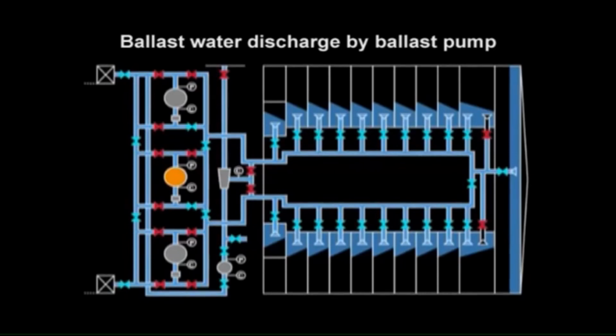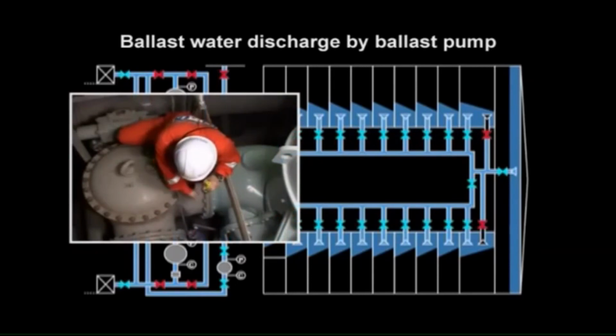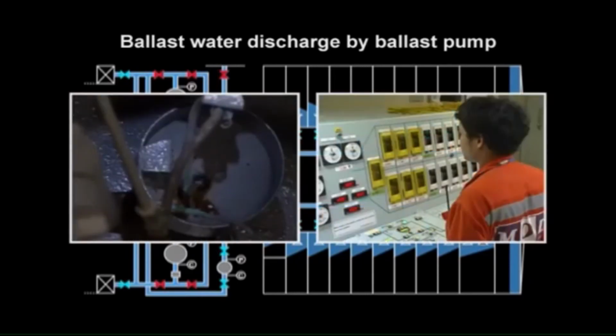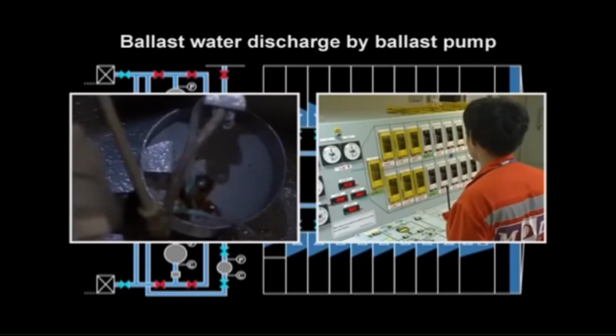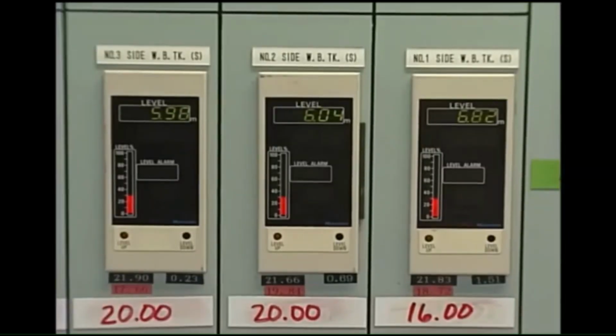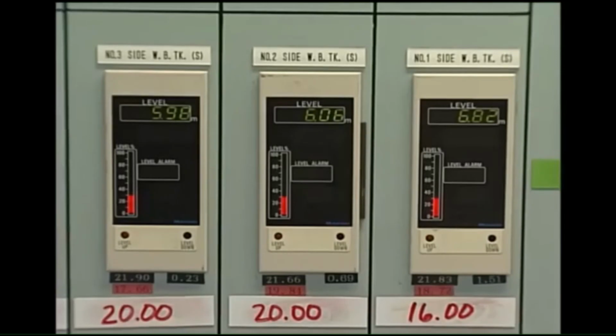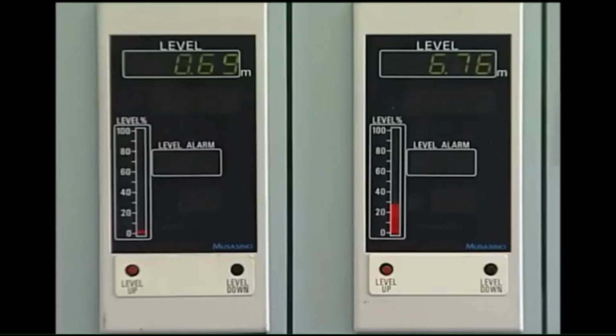The ballast pump starting procedures are the same as for filling. Make sure to conduct air purging from the pump and confirm the state of valves and gauges. Watch water level, since cavitation occurs as the level drops, which causes the water head pressure from the pump suction valves to decline. As the water level drops further to approach the tank bottom, now exercise precautions against air drawing. Watch the gauge carefully and readily respond to the risk of air drawing.